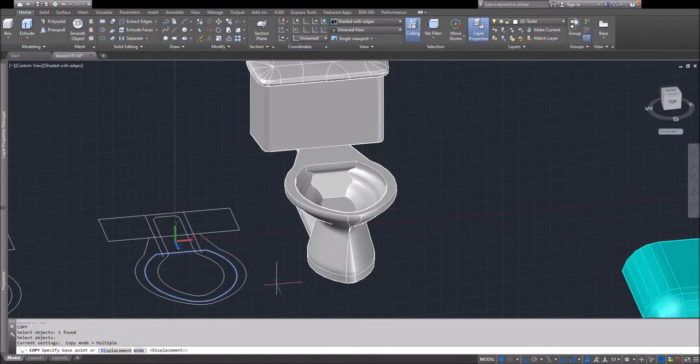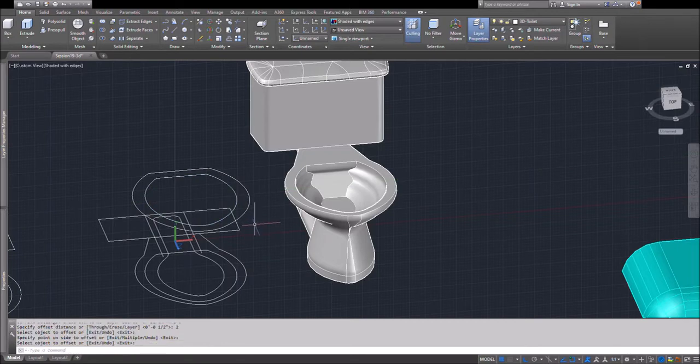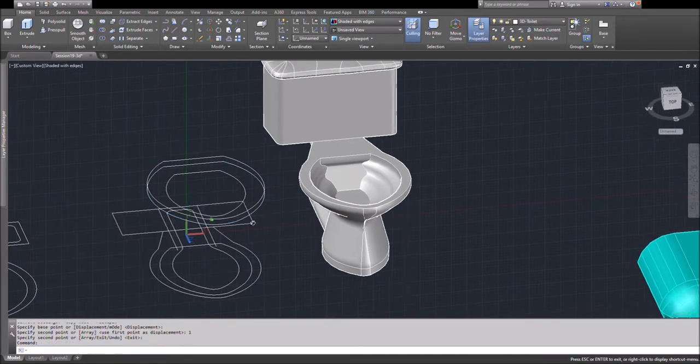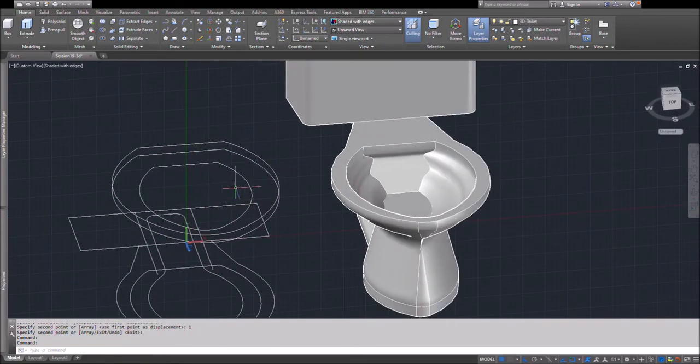So here I'm just taking the polylines again and using those polylines to create the seat now. So again, I'm moving it up to 14 inches to basically the height of the toilet, and I'm taking that profile, and I'll be able to offset that inboard to basically create the seat, and then I'll cut out the opening in the center, so it will look like a seat as opposed to a solid plate. But for the cover itself, I'll be able to use that profile, and again extrude that to create the actual seat cover, right?